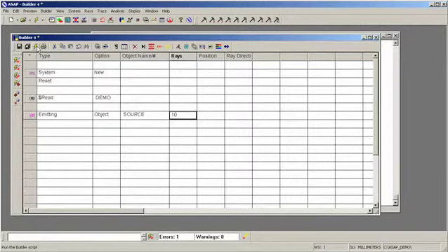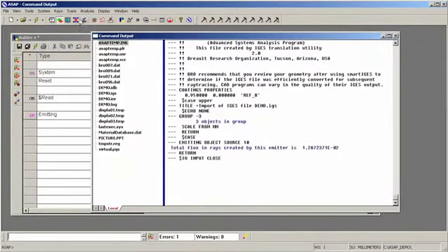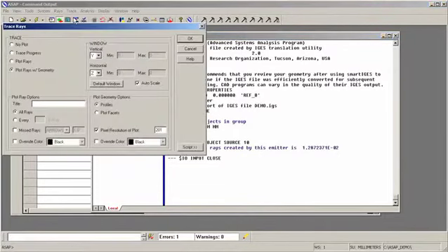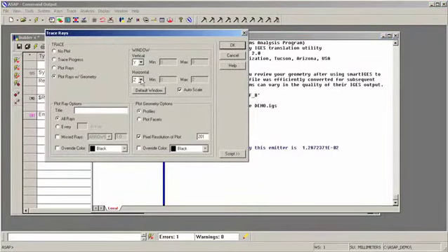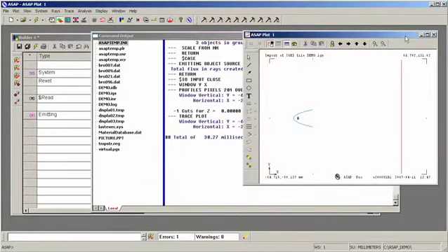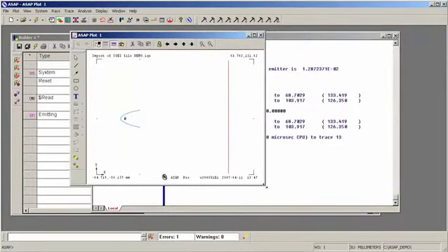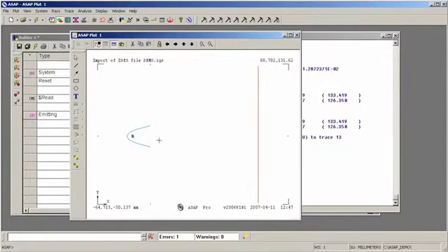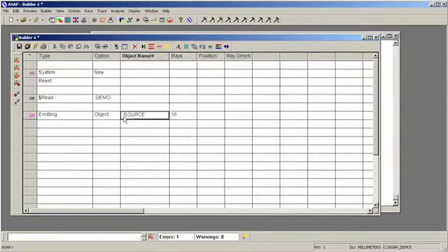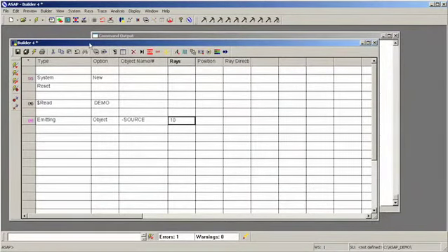The way to do that is to run the builder window, come up to the trace menu, trace rays, and to be consistent with the Rhino view, I'm going to specify the horizontal axis as X, click OK. And here's our graphical ray trace, which does not look too interesting. The reason for that is because in this case the default was to trace rays to the inside of the filament. That's very easy to change. We go back to the builder window and just put a minus sign in front of the object. So the geometry is okay, presumably the source is okay.